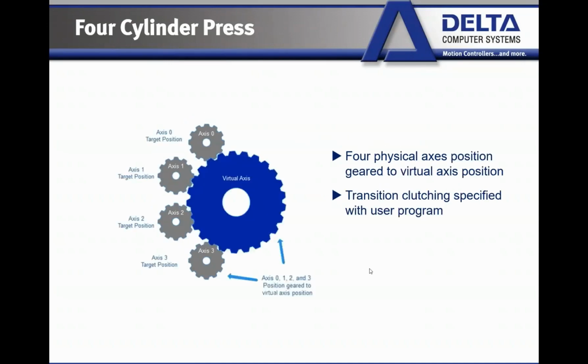Our first step in this process is going to be gearing a virtual axis to these cylinders. Now, what a virtual axis does is it's basically just a target, right? We've been seeing that light blue line, that target line that we had been gearing things to. Perhaps we don't really want to gear to another physical axis. Maybe we want to gear to just a pure target inside the RMC, right? Maybe we want everything linked up to one target axis. We'll call it the virtual axis.